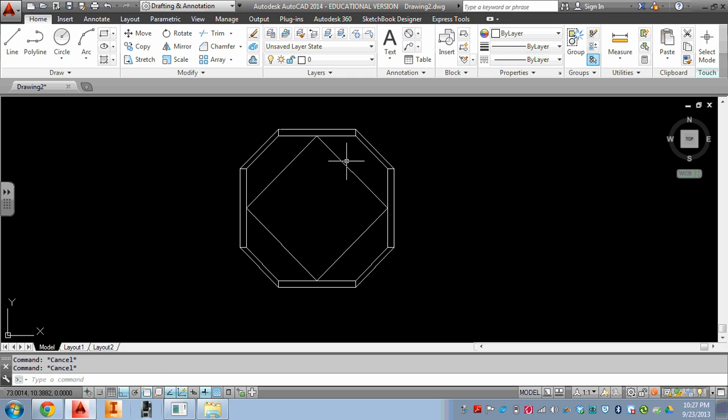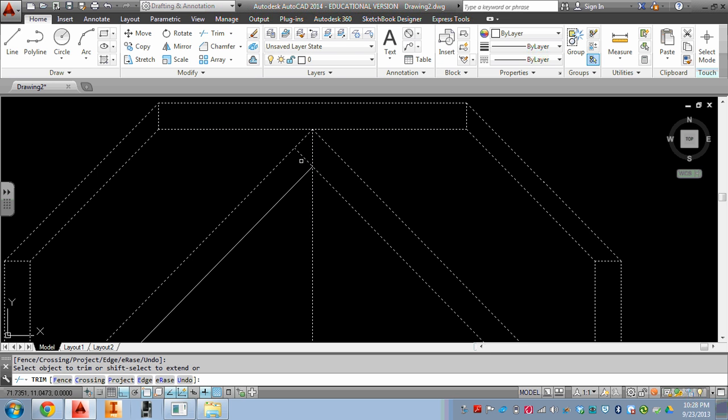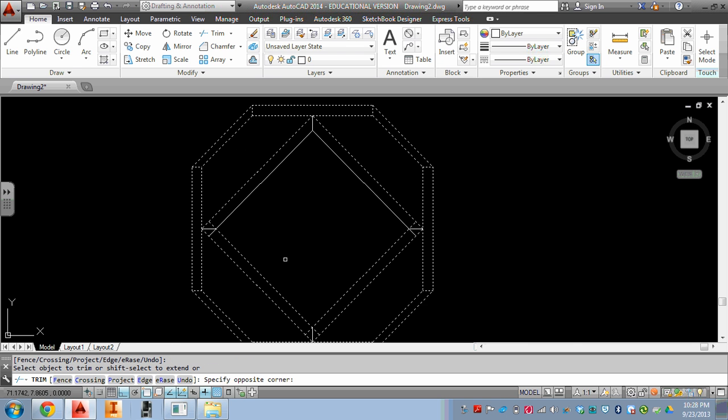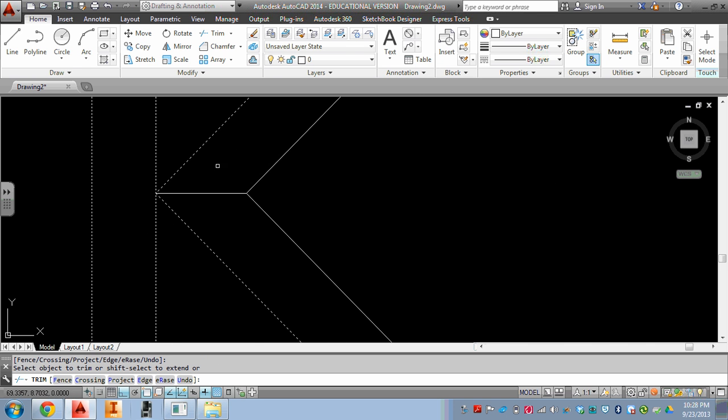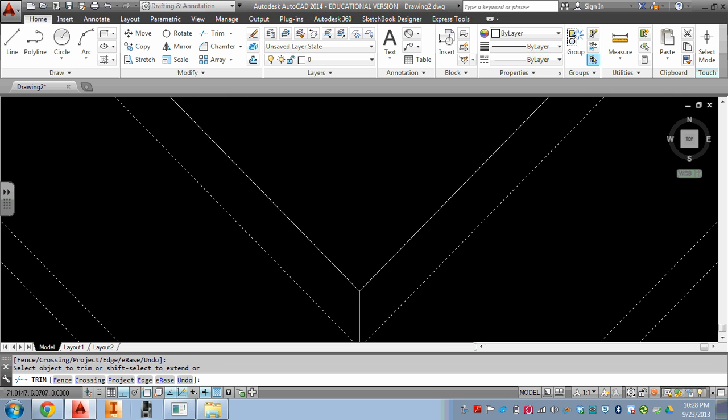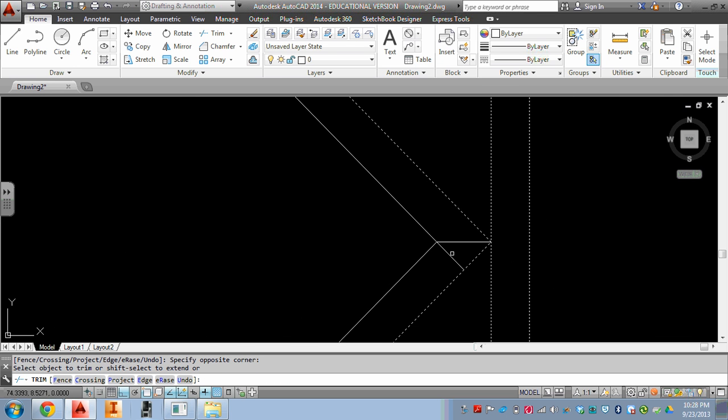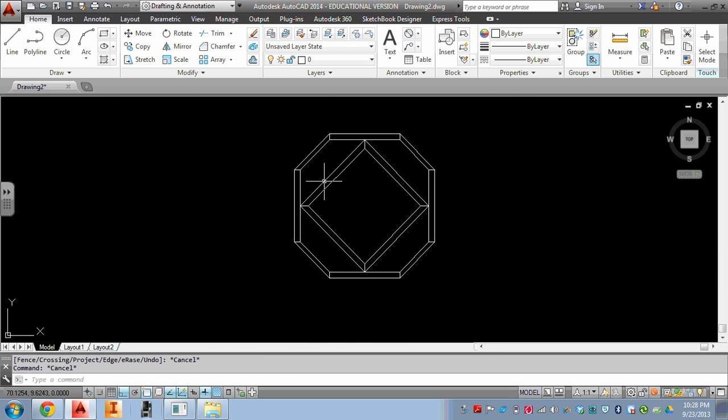And then we can do an offset, 0.25, so offset, 0.25. And we got that. Now I'm just going to do a line. I was going to hit L if you're curious. And come through and do that. Now I'm going to do a big old trim here. I'm cleaning all this up here. You could do different approaches. You could do one side, mirror it around, rotate it around, do an array if you know it yet. So right there, that's our next shape.